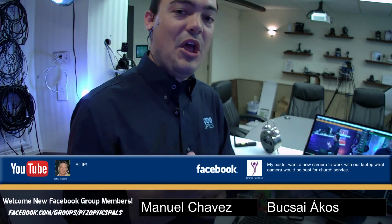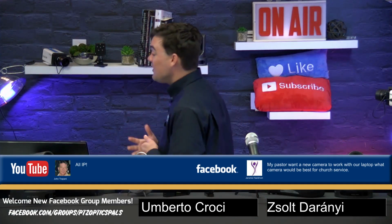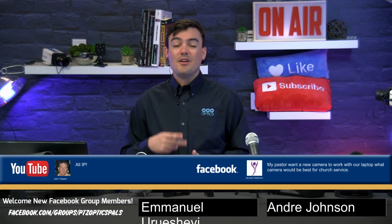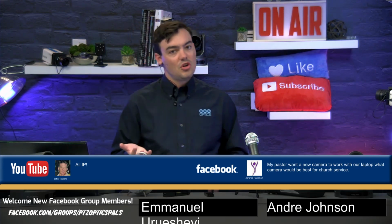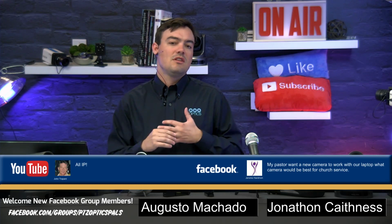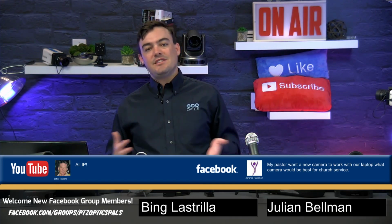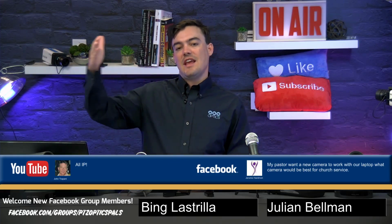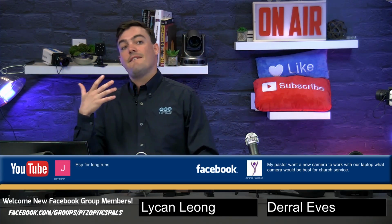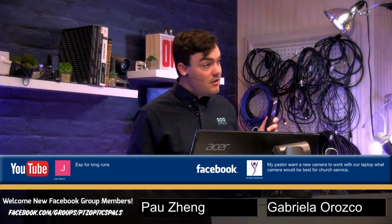But for me still, I just live streamed a concert and I did all SDI. And I also did all serial cabling for the control. I don't know if anyone has ever done RS-232 daisy chaining of serial cabling, but it's actually a little bit of a pain sometimes, because you have to have each camera set to the right VISCA address. And if you're not on the right VISCA address, you can't do it from the joystick. You've got to bring your remote.